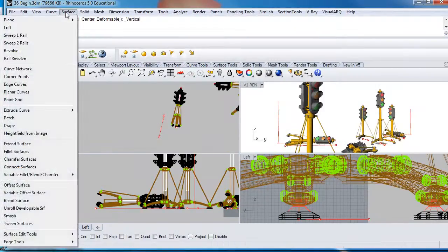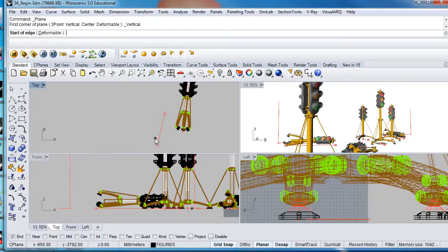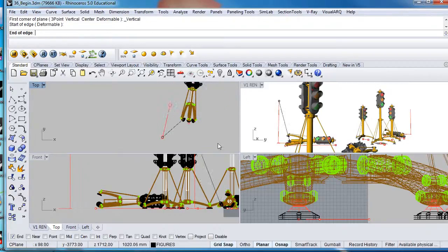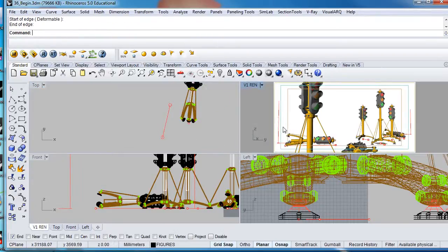So we're going to go to left click surface, plane, scroll down, and you'll see there's corner to corner 3 points, and the third one down is vertical. Now we can key these in with specific dimensions. They'll be used to match the JPEG sizes that are in your reference file folder. But in this particular case, the construction lines for speed of operation are already there in place, so we can simply click on the bottom of those items, shell out.